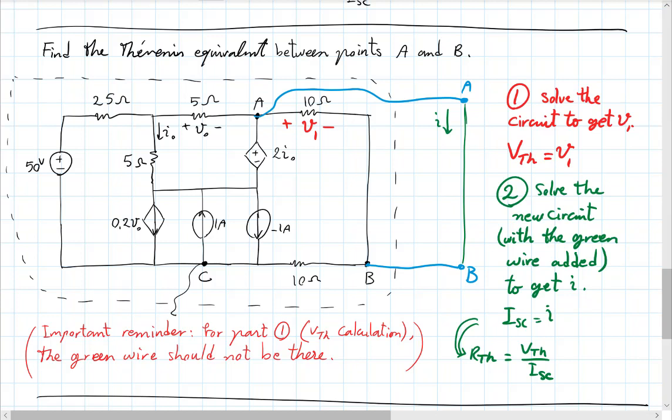So this is really the key point to remember, that the equivalent Thevenin circuit of a circuit, put it this way, if I say give me the Thevenin equivalent of a circuit, that's not a complete question. I should say between which 2 points, okay?